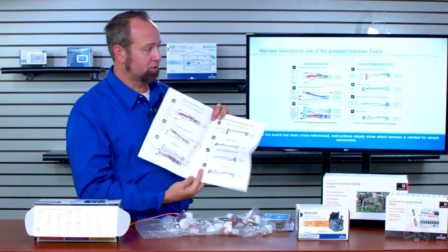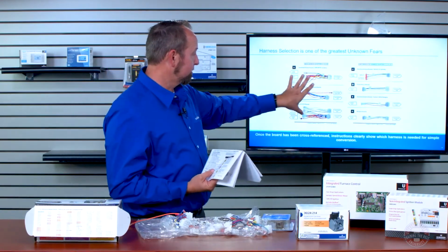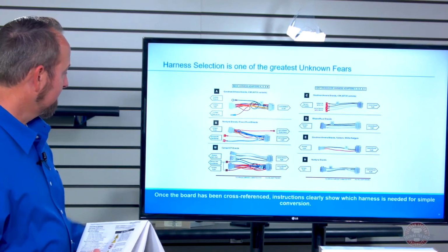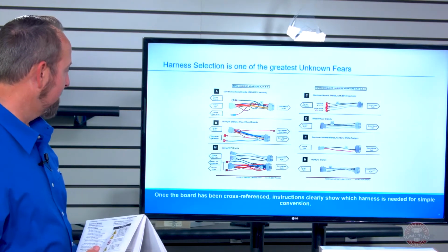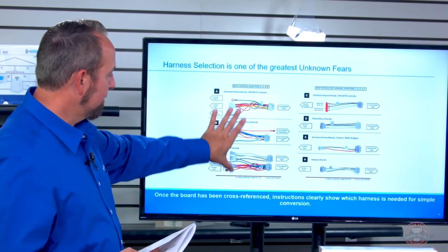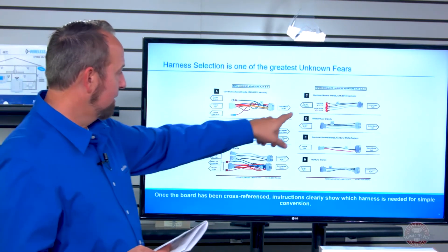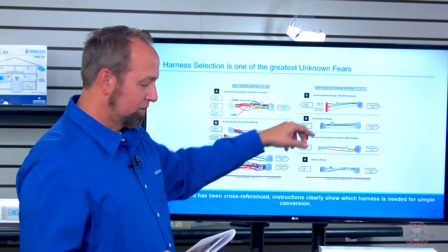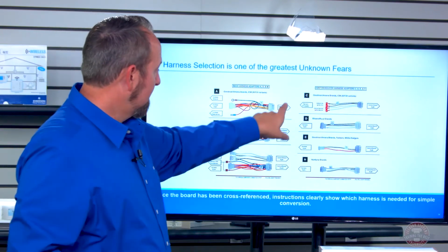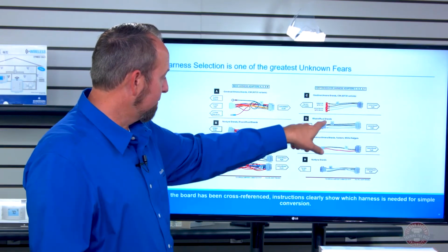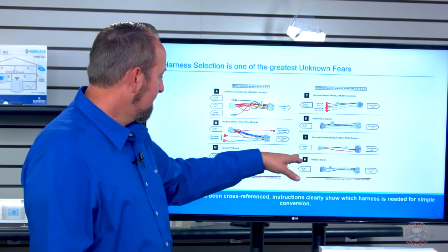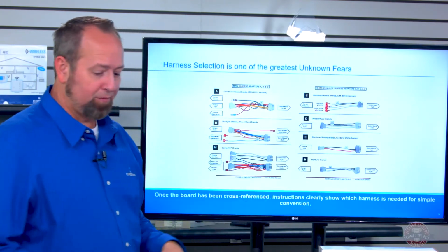Well, here in these instructions, as well as what you see on your screen, A is Goodman, Amana brands and ICM. B is Nordyne, Rheem-Ruud brands. M is Carrier, ICP brands. Those are the main larger harnesses. You also have these smaller harnesses that have the smaller connectors. C is Goodman, Amana, D, Rheem-Ruud. E, another Goodman, Amana, going to a 2-pin furnace.